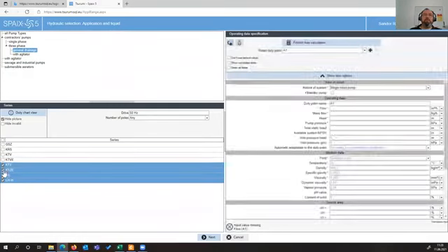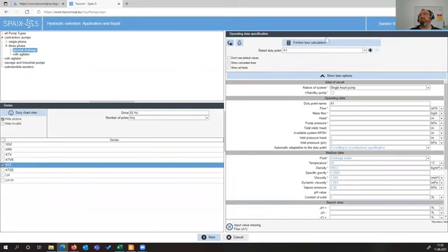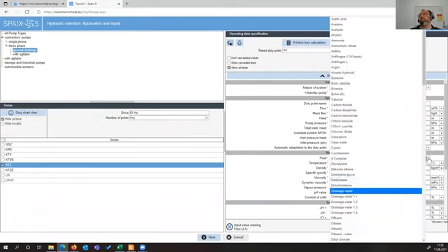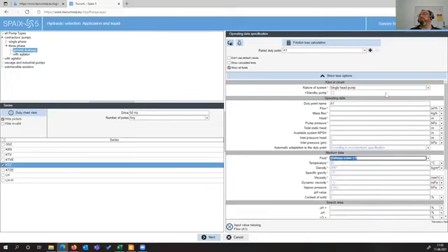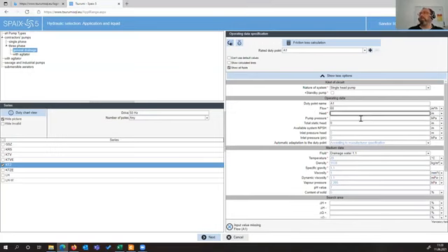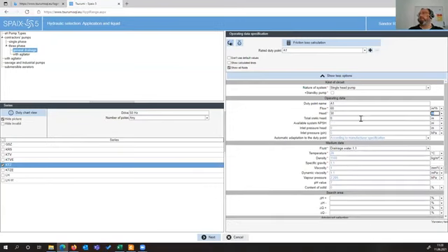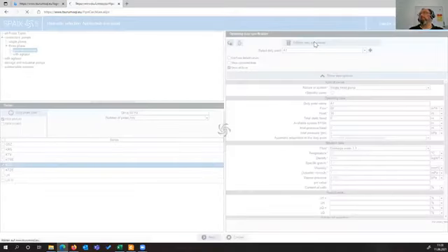And my favorite pump is still the KTZ. And we want to use drainage water with a density of 1,100 kilogram per cubic meter. We said the flow rate is about 60. The delivery head is about 30 meters. And these are the main data we need for the friction loss calculation.